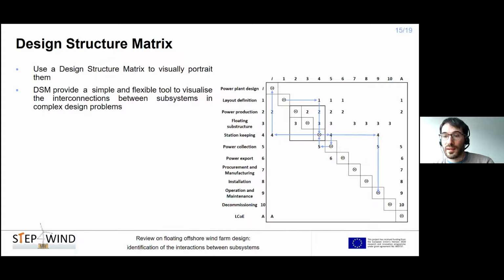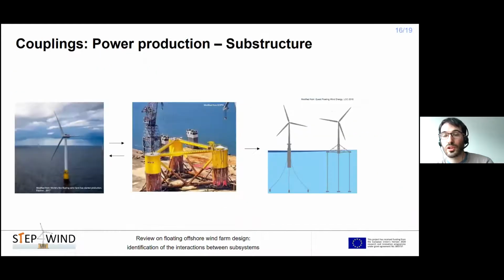Furthermore, designing mooring systems that can be efficiently connected and disconnected from the platform over the 20 and more years long life of a wind farm will enable towing the platform and turbine to the harbor for maintenance, which in turn will affect the operational expenditure and thus the levelized cost of energy.